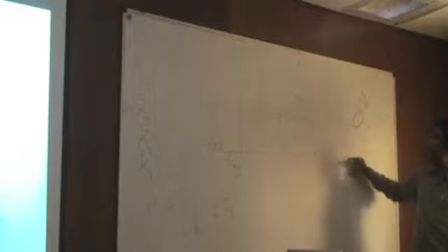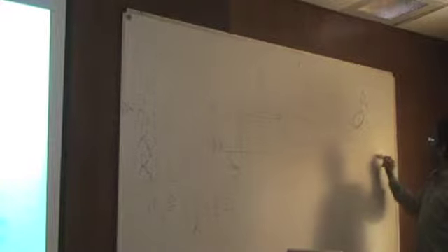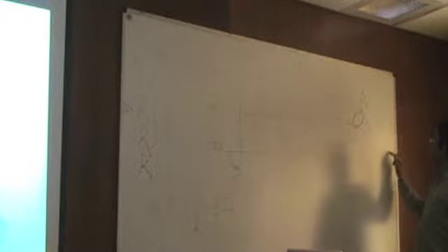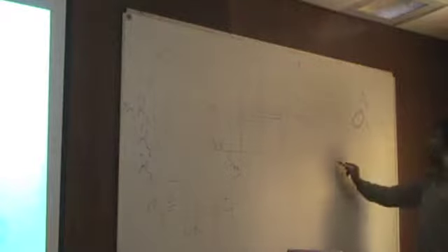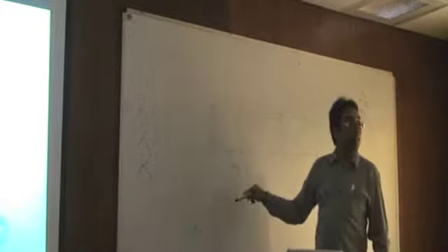Now your x3 values are reducing for the same material points. The material point which was over here has now come to here. In other words, its x3 value has reduced. So when you integrate x3 squared dA over the entire cross-sectional area, it is going to be much lesser now. In other words, your bending stiffness is going to be lesser.